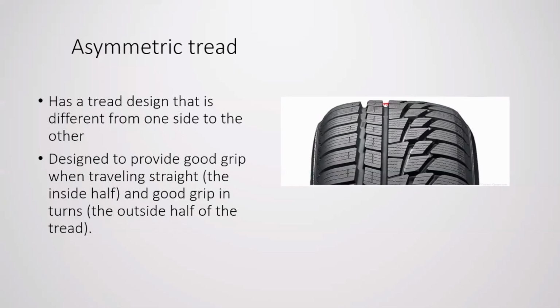I was explaining about the tire wear indicators, right? Somewhere like this, we have a tire wear indicator, something like a rib, which has a lower tread height. Once our tire is fully worn, this tread pattern will be level with the tire wear indicator, right?